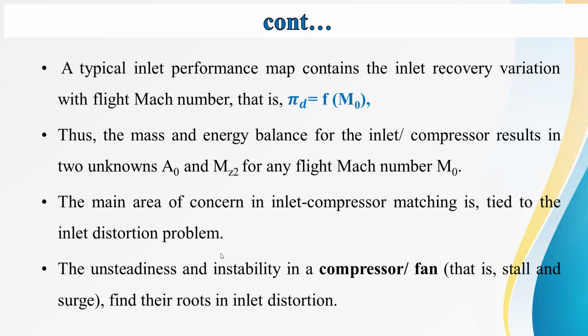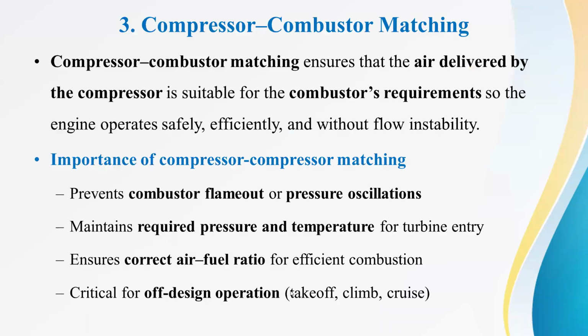So the main area of concern here is inlet compressor matching, which is connected with the inlet distortion problem. The unsteadiness and instability in compressor and fan, which we call compressor surge, find another problem, which is in inlet distortion condition.